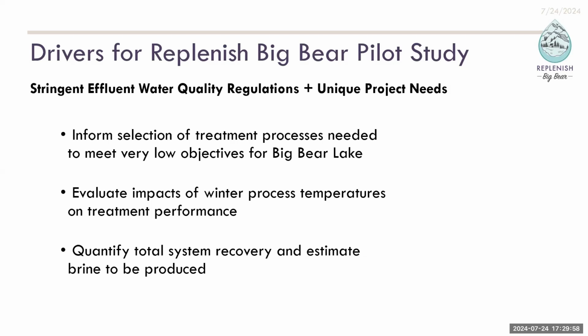So this informs the selection of the proposed treatment process needed to meet those objectives. Very importantly, from a wastewater treatment perspective, cold weather is not good for some treatment technologies, so we have to understand how they fare in a cold weather climate. And then lastly, to quantify that total system recovery and estimate the brine to be produced.